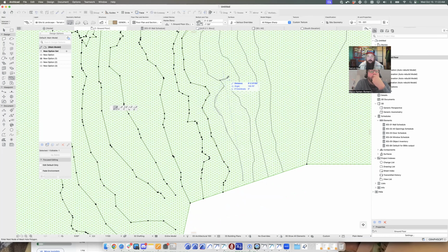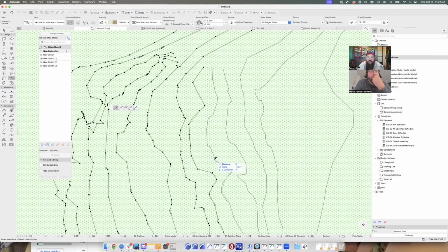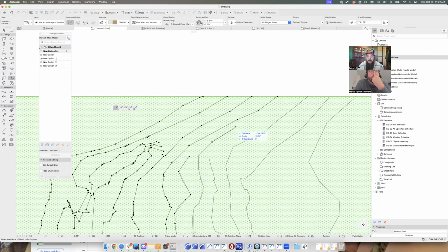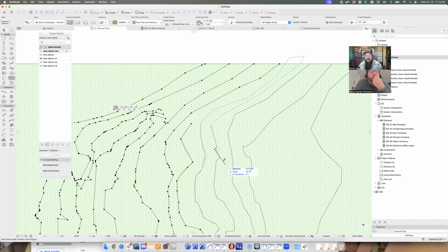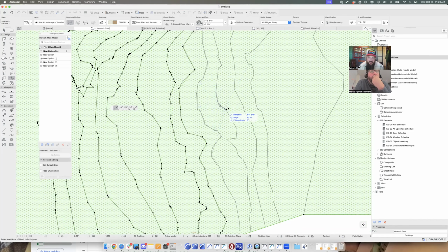This is a workflow that I found only recently that lets you do this in rapid succession. I could take this contour and run it to the edge and then run it back in, and do the next contour. Because it's running past the mesh, it can't add contour nodes, so it's actually going to create these as separate contours.